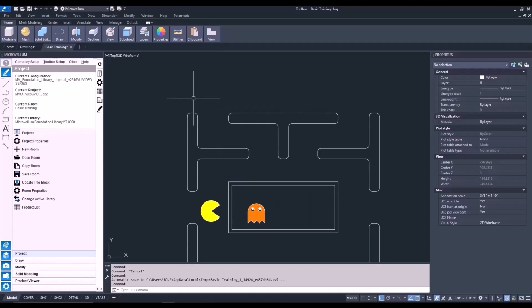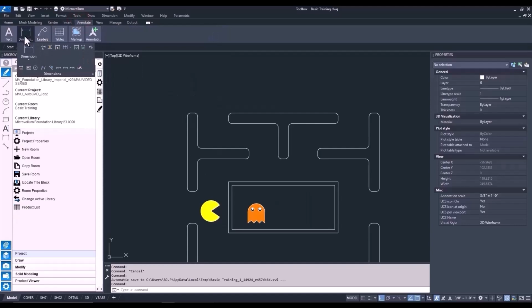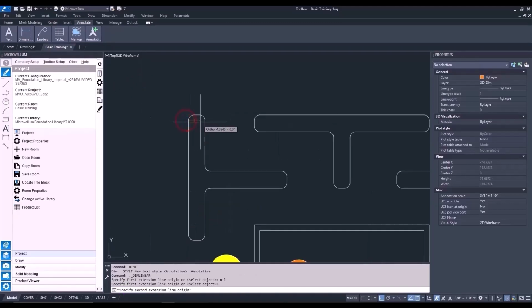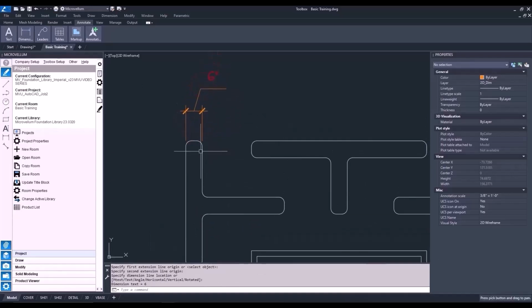For me, if it's more than 3 letters, I'm probably finding another way to use that command. So another way is in the AutoCAD ribbon under the Annotate tab. So you can type in the shortcut or select it from the ribbon, and now pick 2 points to dimension. Left click on the first point, then again on the second point. Move your cursor up, and left click one last time to pick that landing spot.